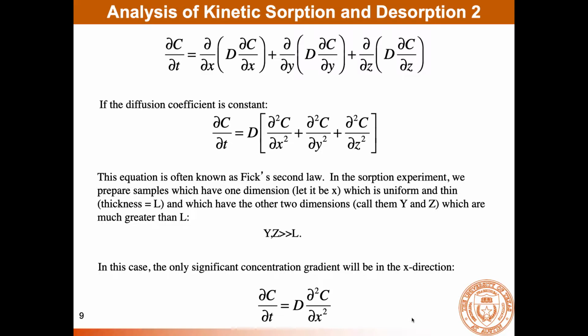And if the y and z directions are large, they also have very little surface area for mass transfer to occur. And so the mass transfer occurs across primarily the surface that is perpendicular to the thin dimension of the sample. That's just the way the geometry works. And in that limit, when the thickness is much less than either of the other dimensions, the only term that's important is this first one.